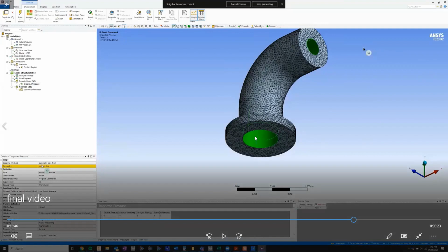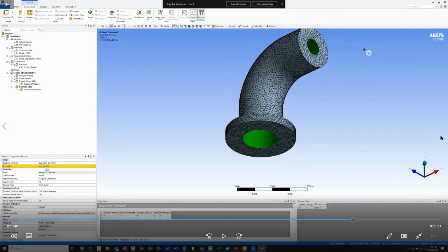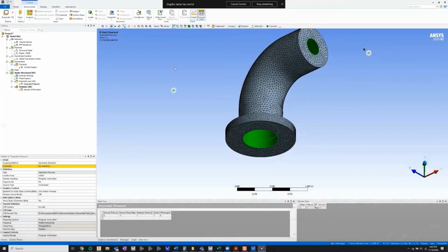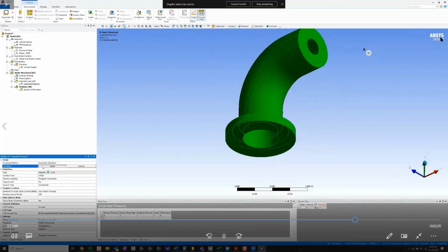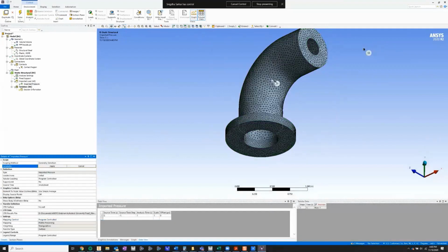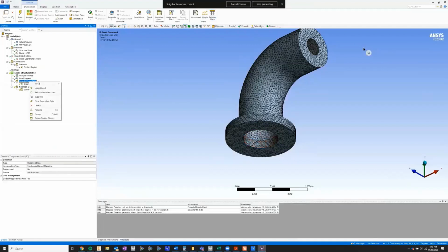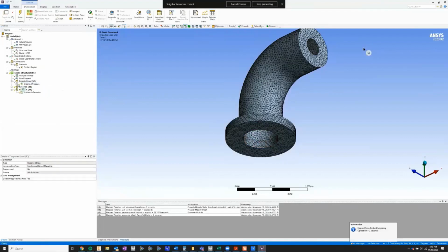So you can see John selecting those same walls that I named as FSI wall on the CFD side of things, because that is the wall that is common to both these simulations, and that is where the pressure values will be imported. So you can see that the FSI wall automatically shows up in the CFD surface. And when we click on imported load, we get a green check.